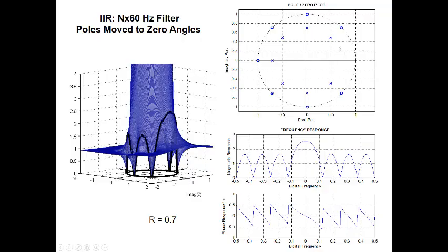So if we spread out our poles along the same radii as our zeros, got them away from z equals 0, you'll see we've gotten the notches a little bit narrower. The poles are also helping make the tops of these peaks a bit more uniform, although not having a zero here at DC is still giving me an extra bulge, as the rubber sheet's not pulled down at that point.